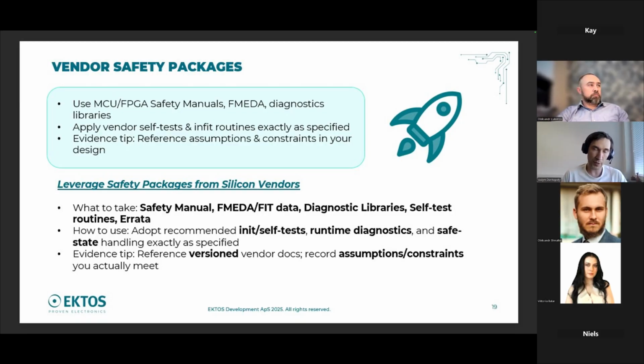This safety package contains data which is needed for certification, like FMEDA results, FIT, diagnostic libraries, self-test routines, errata sheets, and a list of tools which should be used for your product. Start from this one to read how to use this and what features you have to take to be on the safe side.